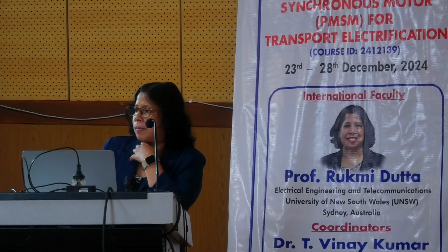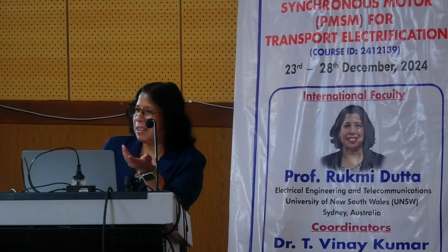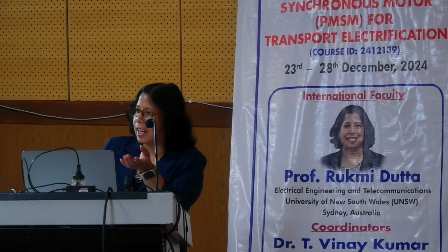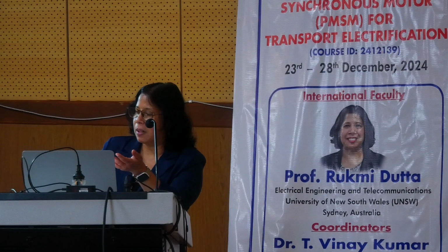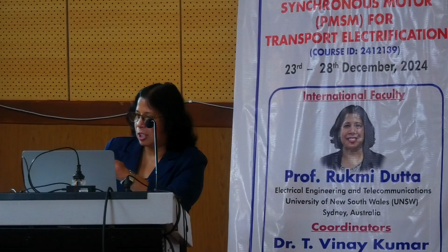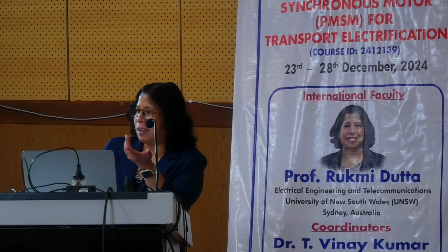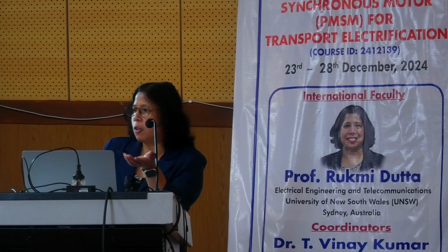But the current drawn is very high, ma'am. The position will not correctly match. The current drawn will be high, ma'am. Yeah, that's why the performance will not be good, right? It could even vibrate. You may get noise, okay? Or it may not be operating with the torque it can produce because you are not controlling the torque as maximum torque per ampere, right? So it is drawing very high current, as you say, because it's trying to produce a torque based simply on the V/f ratio, right? But you are not controlling anything.